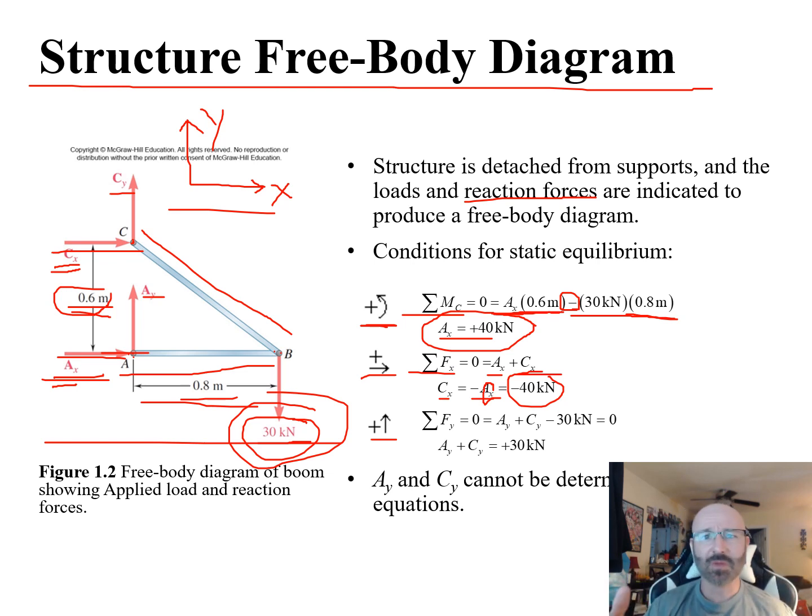So as we get to this point, okay, what am I really solving for? Go back to my beginning page here, my setup page. Oh, I'm solving for my reactionary forces. So I'm going to need my CX, CY, AX, and AY. That's what they asked me to solve for in this problem. So that's what I'm going to go back and make sure I have. So far I found my AX and my CX, but I don't have any of the Y components. So that's why we're going to jump into our summation of forces in our Y direction here.